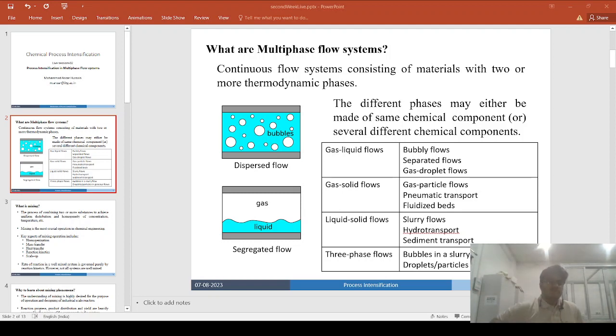Now, using silicon microfabrication, it is possible to construct packed bed microreactors that provide 100-fold or more improvement in mass transfer for gas liquid heterogeneously catalyzed processes such as the hydrogenation of unsaturated carbons.